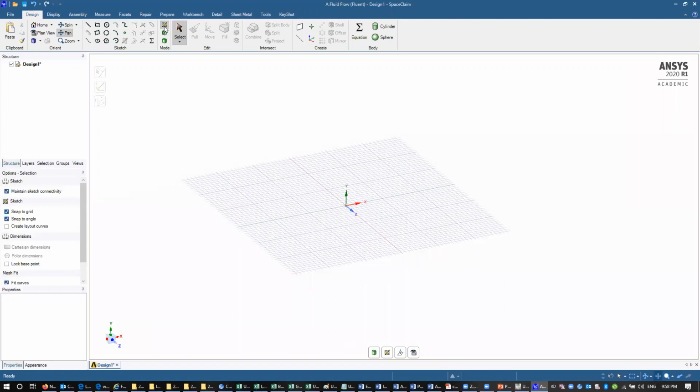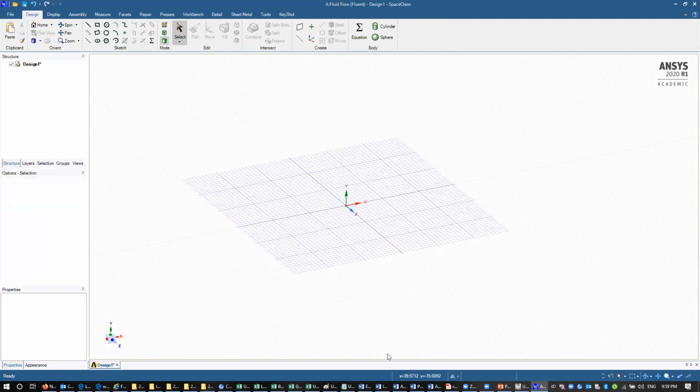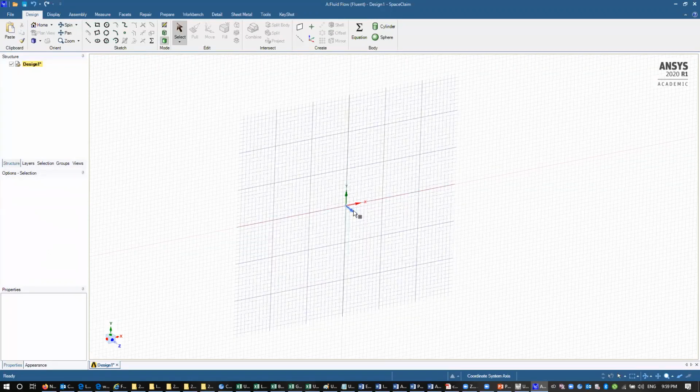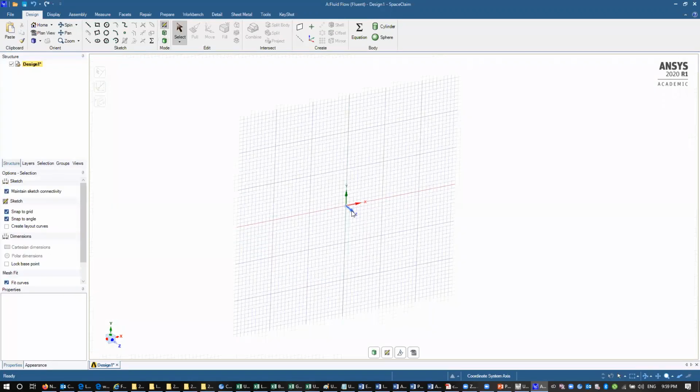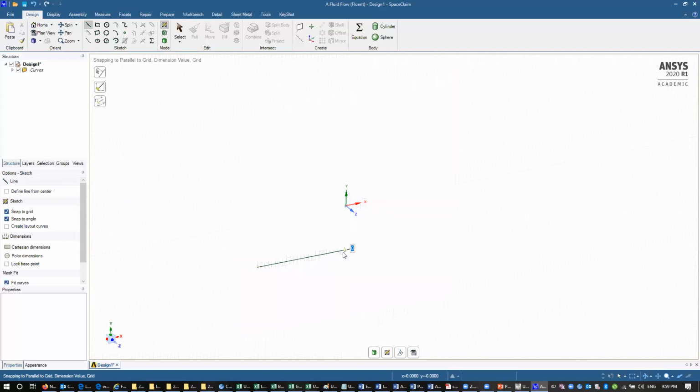This is for drawing sketch. And I need to choose the plane for drawing sketch. The axis of the main pipe is on XY plane. Draw a straight line. One end is -12 to 0, and y is -6.